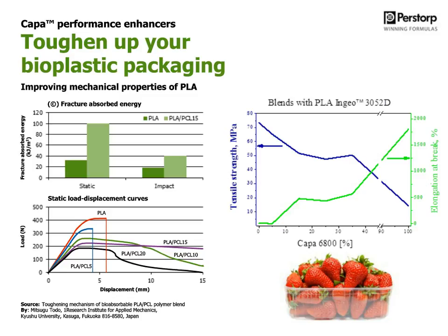But if you look at the fracture absorbed energy, you can see a drastic improvement by adding just 15% of PCL in the PLA. And with the impact strength, it's twice as much, which makes it interesting, always keeping the cost balance of your formulation in mind.